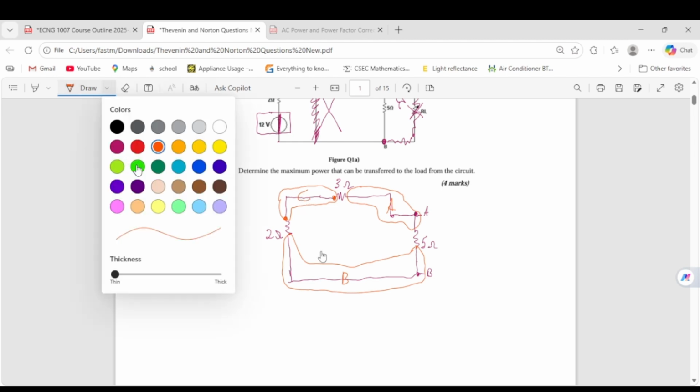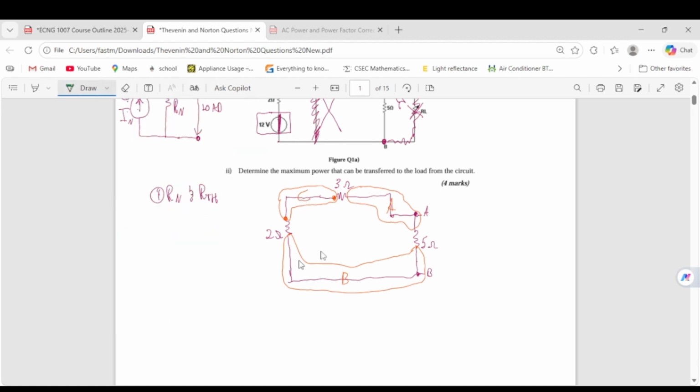So the trick is, we know A is the input, quote unquote, we know B is the output, quote unquote, and C is in between both of them. What this system helps you with is, if you find it hard to know whether a resistor is in parallel or in series or whatever the case is, you can just use this method. So first, you draw up the nodes, you have your inputs and your outputs, and you put all the other nodes in one line.